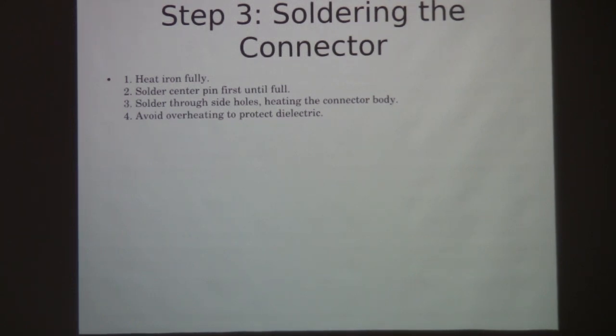I would recommend a soldering gun works really well for doing that, or one of these big soldering tips, because that thing absorbs a lot of heat. But once you get it hot, you'll know it because you'll put the hot solder in there and it'll just flow right in.